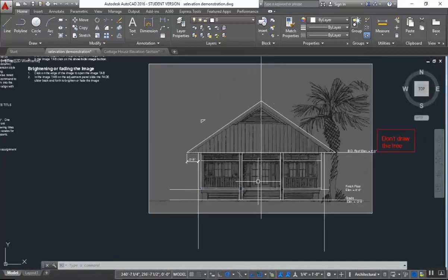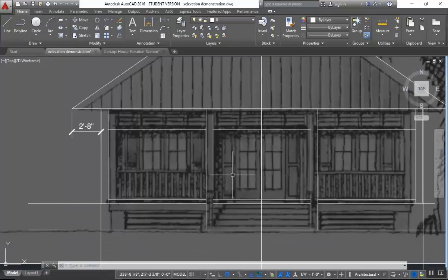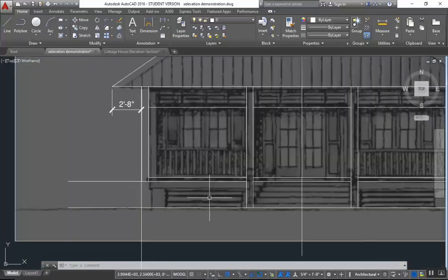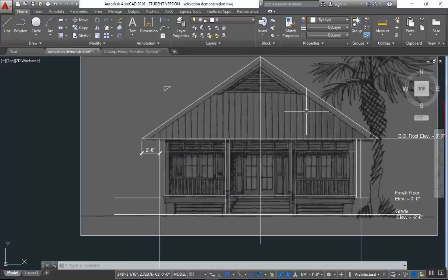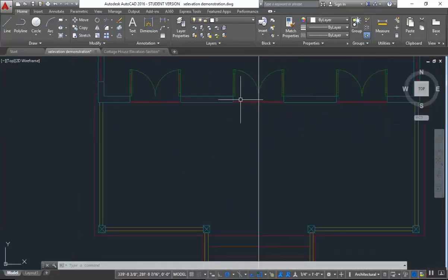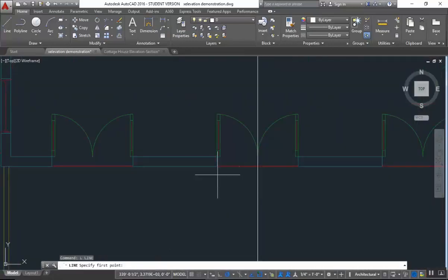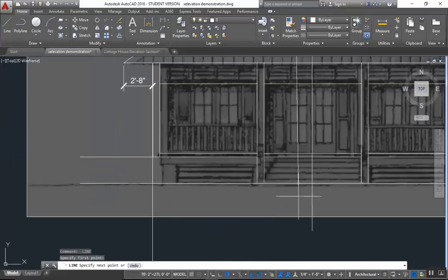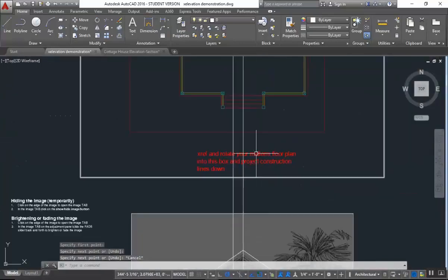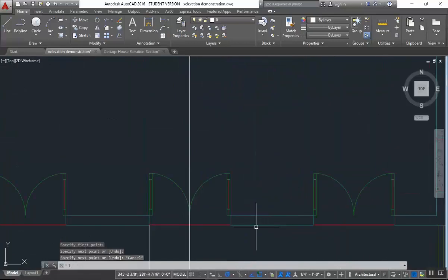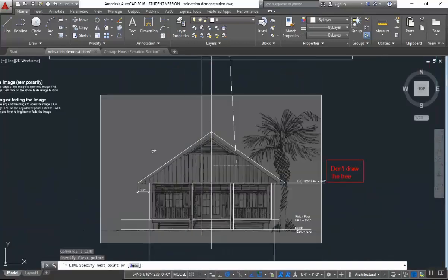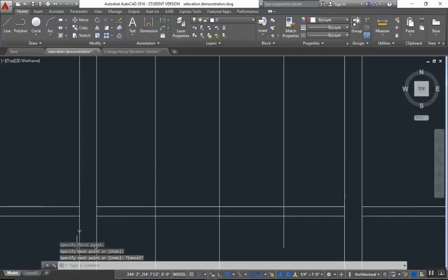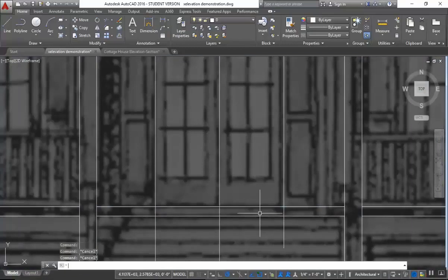All right, so we're getting close to having the outline of the building. We want to add our doors, and our shutters here, and we can draw the line for the top of the rail also. So the doors, we know how wide they are because it's shown here in our floor plan, so we just draw a line from right here straight down, like that. And we draw another line straight down from the other side, like this. All right. The bottom of the door goes to there, so I can trim that out.